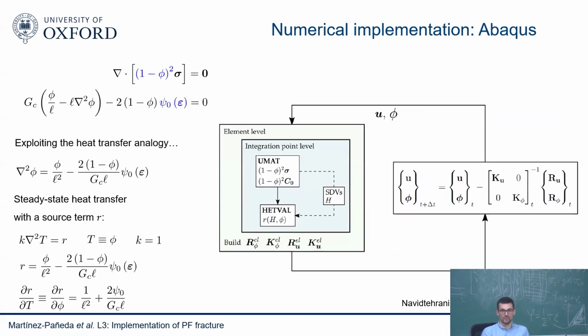You click a button and you say, Abaqus, I want to solve my problem, which is not a real thermomechanical problem, it's a cheated thermomechanical problem, monolithic or staggered. In which case, Abaqus will add some coupling terms. But I don't think Abaqus has coupling terms here because you don't define those coupling terms. In any case, you can solve both at the same time or both sequentially, one after the other. So Abaqus will have an option there to solve staggered or monolithic.